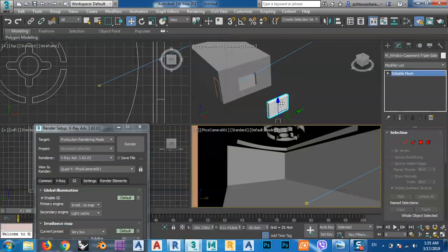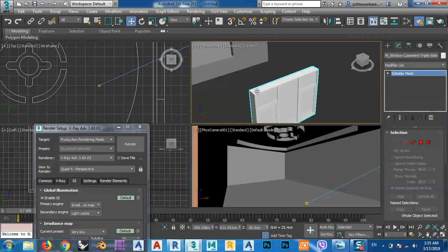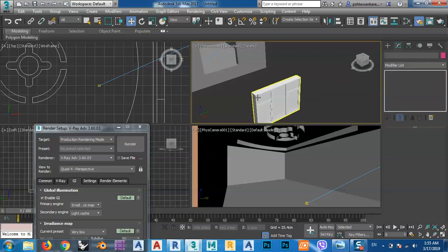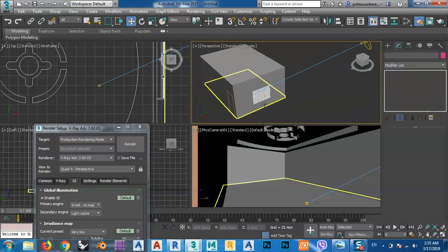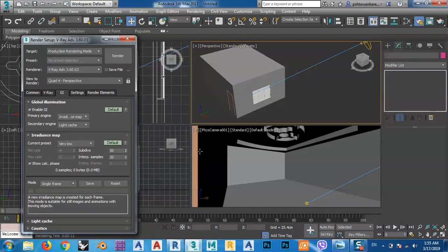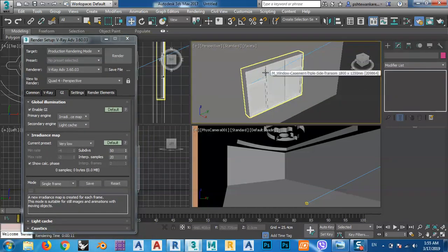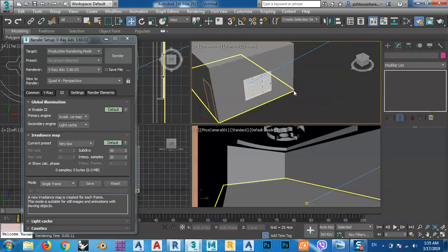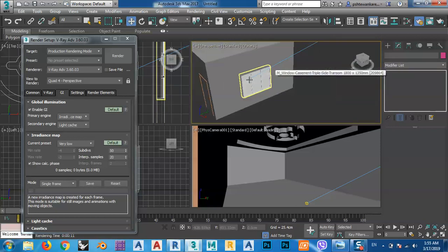So what's the problem? This problem is because we don't give it any window material, so it treats it as a solid. So just go back like this. Anyhow, I want to put some materials on this one, a window.